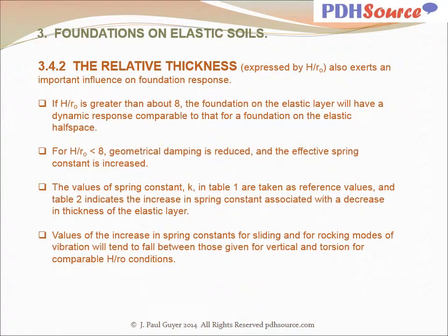The relative thickness, expressed by the ratio H divided by r_o, also exerts an important influence on foundation response. If H divided by r_o is greater than about 8, the foundation on the elastic layer will have a dynamic response comparable to that for a foundation on the elastic half space. For H divided by r_o less than 8, geometrical damping is reduced and the effective spring constant is increased. The values of spring constant K in Table 1 are taken as reference values, and Table 2 indicates the increase in spring constant associated with a decrease in thickness of the elastic layer.